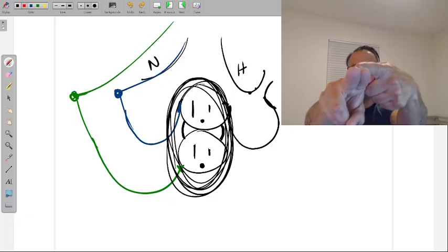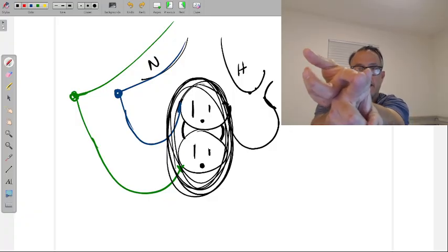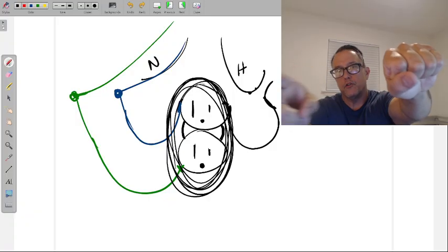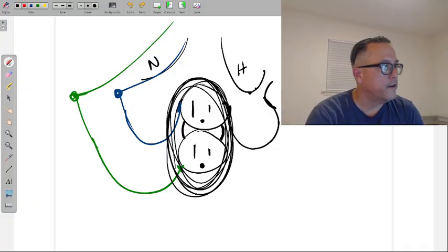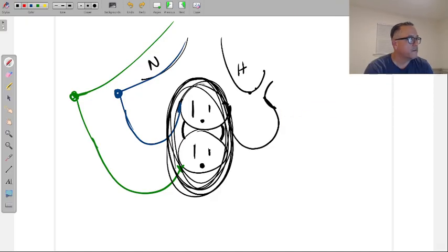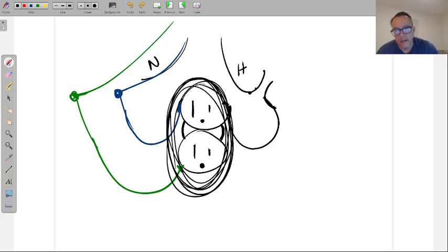And as you turn the wire strippers, the insulation that's in the front is going to get pushed forward, and now you should be able to just jog it on out. With care, obviously, and you can practice it when you get down to the lab on Monday. Just get your wire strippers, hold them sideways, cut, turn, and you'll see it separate the insulation. Better on solid wire than stranded wire, which I don't think you've worked with yet. You will next module. All the control labs are with stranded wire.